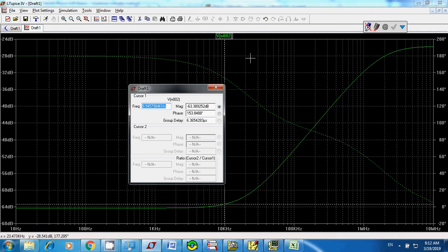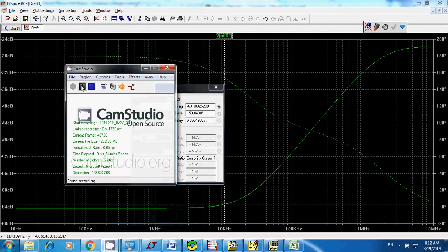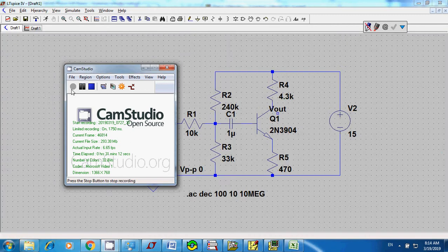They also ask you to do the circuit at 75 degrees. So just change that one to 75 degrees instead of room temperature, or 27 degrees. As I mentioned, a student needs to do the circuit at 75 degrees, looking for the gain in decibels at 10k, and also the phase difference at 10k.